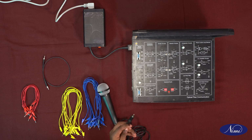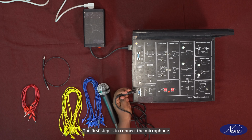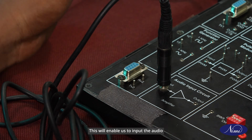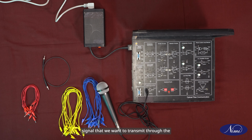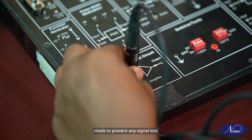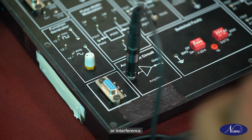Connect the microphone. The first step is to connect the microphone to the audio input circuit of the OFC Trainer Kit. This will enable us to input the audio signal that we want to transmit through the optical fiber communication system. Ensure that the connections are securely made to prevent any signal loss or interference.